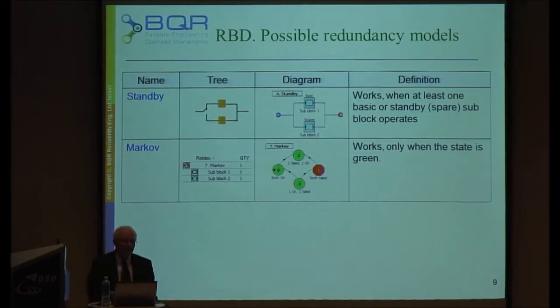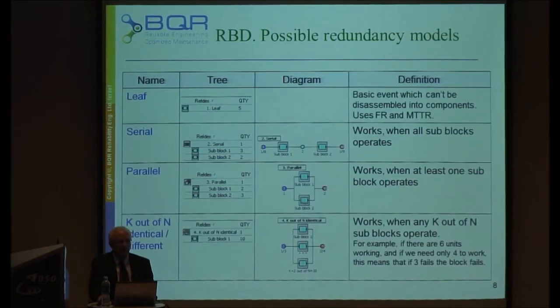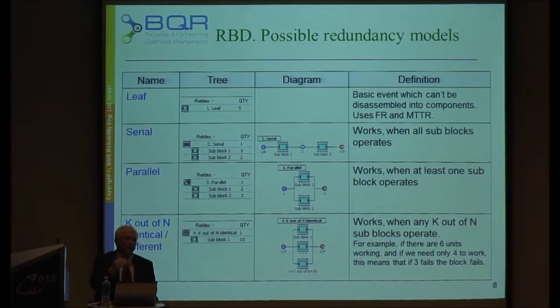So as a recommendation, with electronic parts, it's better to operate them. If you have something which is switched off, try this model, because this model will operate the components. It may be in a lower stress, in a lower temperature, but the internal heating of the components will prevent the humidity from going in and making corrosion.